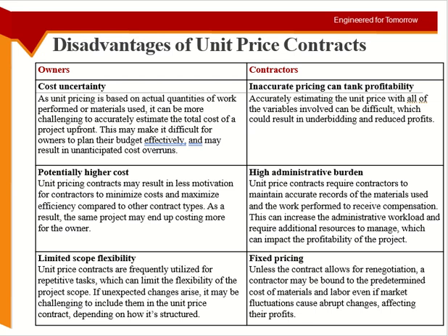Okay, so maybe the number of units are same, but something happened in the market. Like I gave the example of steel. So the same unit of work is not costing me the same amount now. Okay, so there is a type of change which is in the scope of work. So the type of change which is in the scope of work is covered here, no problem. Okay, if I increase the scope of work or decrease it, I'll get the price with the same unit rate.